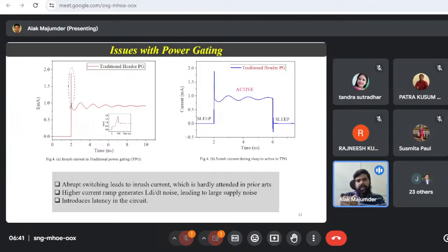So that is a very basic, real-time example of this sudden spike. Another example: you might have seen that the PC which you use in day-to-day life, in our labs, or we might have observed that the SMPS has gone wrong, right? Why will the SMPS go wrong? This will definitely happen if your original power supply is fluctuating continuously.